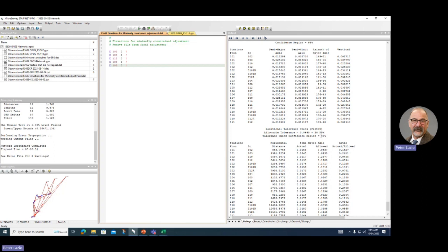And I would then have to move receivers, but the work would be done correctly. They insisted, no, it's simpler if you use 4 receivers, just leave them on the 4 stations and do 2 sessions. So based on the specs for doing azimuth pairs, that would give me just the minimal amount of stations I needed.